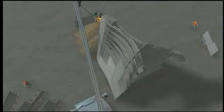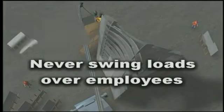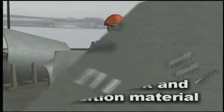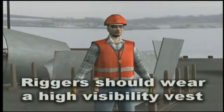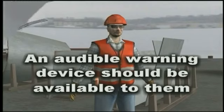The crane operator swung the boom and load over an area where the employee was working. Crane operators must never swing loads over employees. The work should be planned and plates pre-positioned on both the starboard and port sides so there is no load passing over the workers. It is recommended that riggers wear a high visibility vest and have available to them an audible device such as a whistle to alert crane operators or nearby workers of unsafe situations.